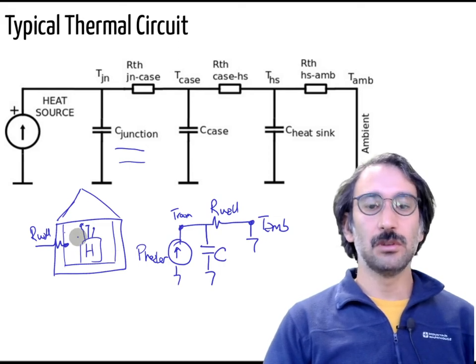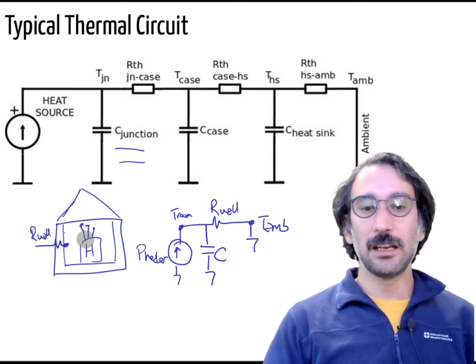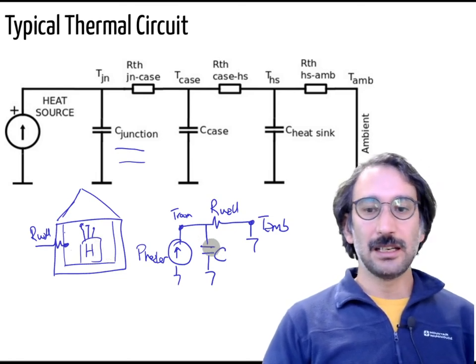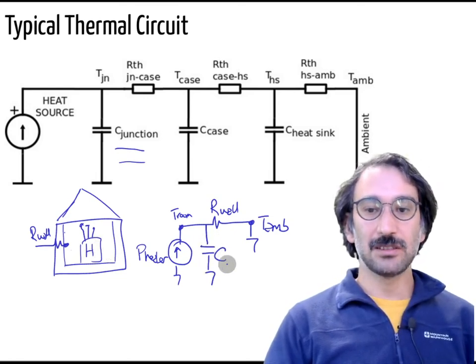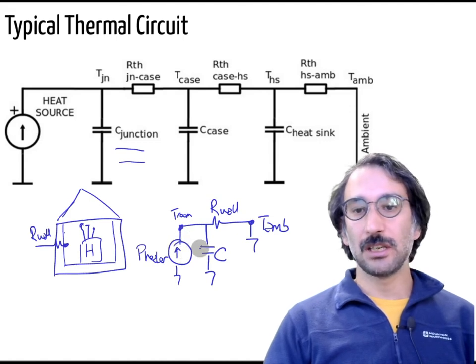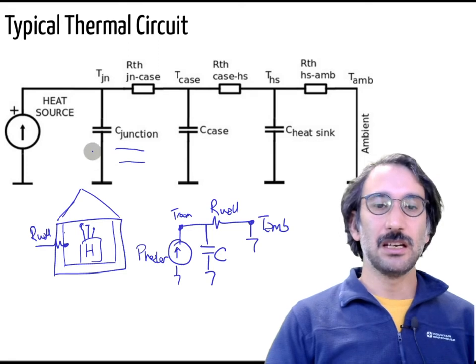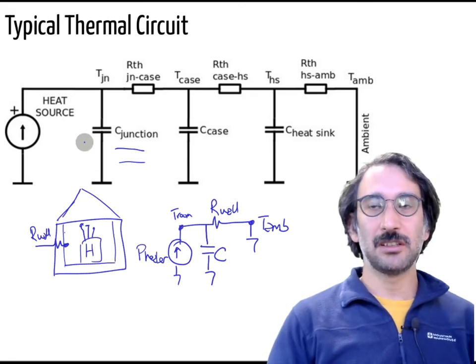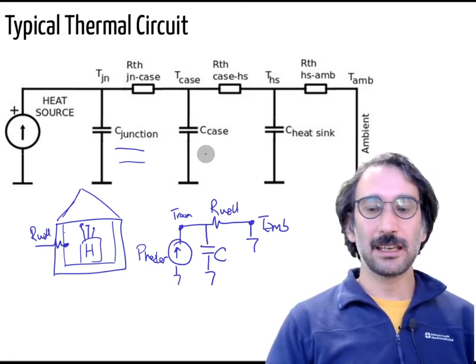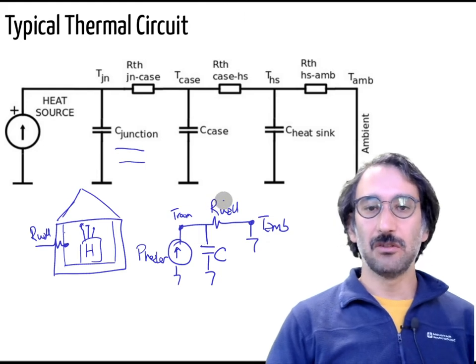First you need to warm up the air, then you need to warm up the walls and other furniture, and actually it just behaves like a capacitance. You cannot increase the voltage of a capacitor immediately, and you cannot change the temperature of a material immediately. There's some lag on that, so it is like a low pass filter.